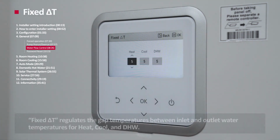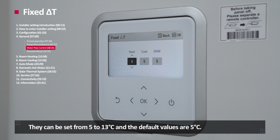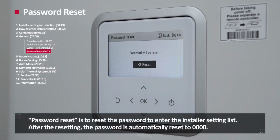Fixed delta T. Fixed delta T regulates the gap temperature between inlet and outlet water temperature for heat, cool, and DHW. The system automatically changes the flow rate in order to ensure a stable delta T. They can be set from 5 to 13 degrees Celsius, and the default values are 5 degrees Celsius. Password reset. Password reset is to reset the password to enter the installer setting list. After the resetting, the password is automatically reset to 0000.